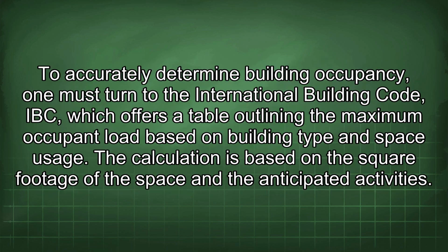To accurately determine building occupancy, one must turn to the International Building Code (IBC), which offers a table outlining the maximum occupant load based on building type and space usage. The calculation is based on the square footage of the space and the anticipated activities.